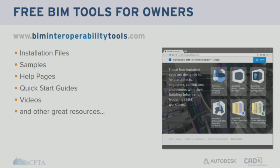When I demo the tool, I have a version of the COBie model that's missing a single door parameter. And I ask people, how long would it take you to find a single missing parameter in 40,000 parameters? And I find it in a minute and a half. The Penn State model checker, which is free to everybody in downloads, has over 6,000 checks in it. It takes about 2.5 minutes to run on a decent sized model. That's a lot of checks.